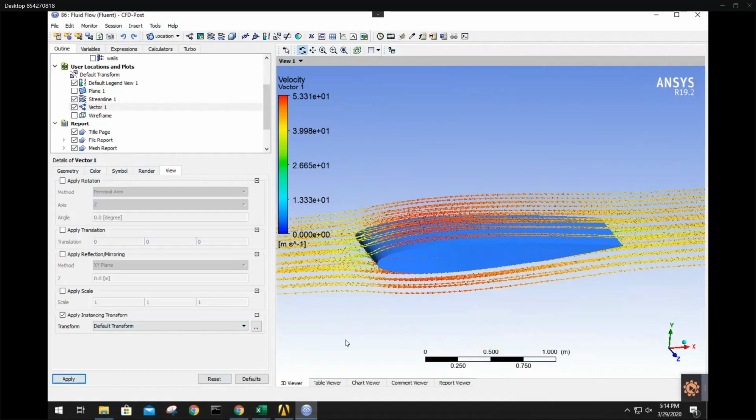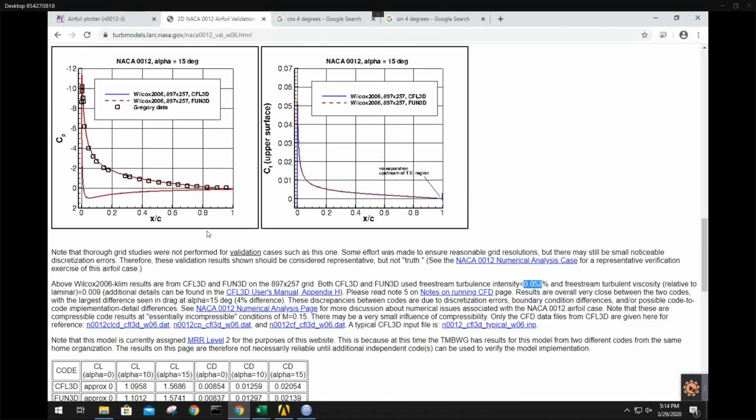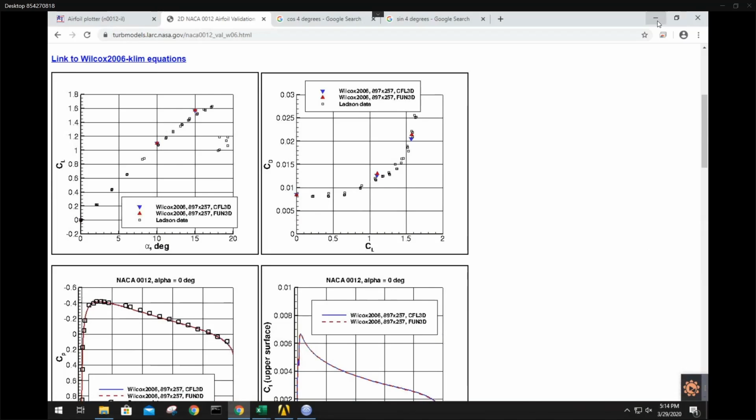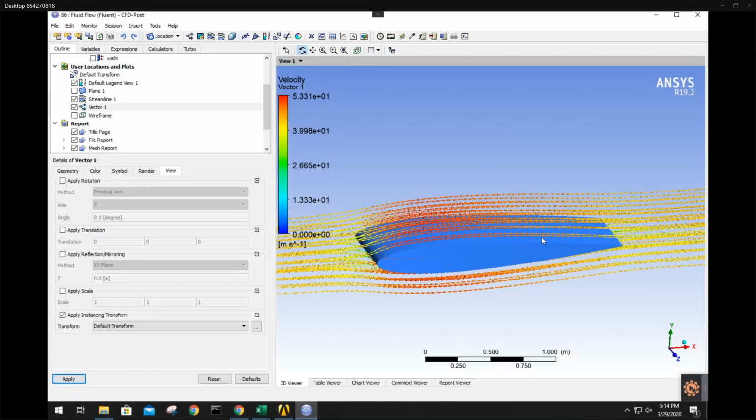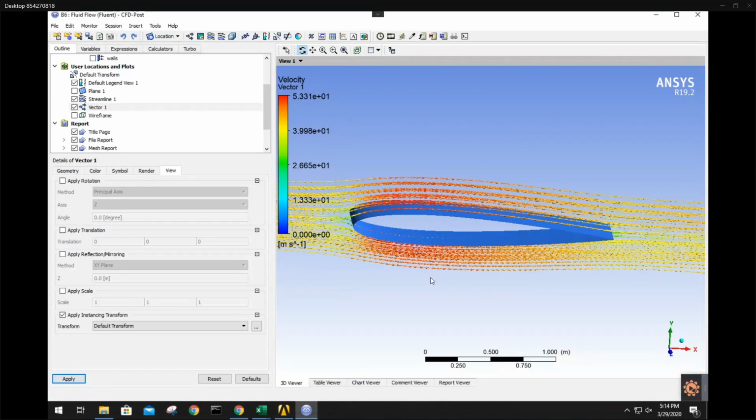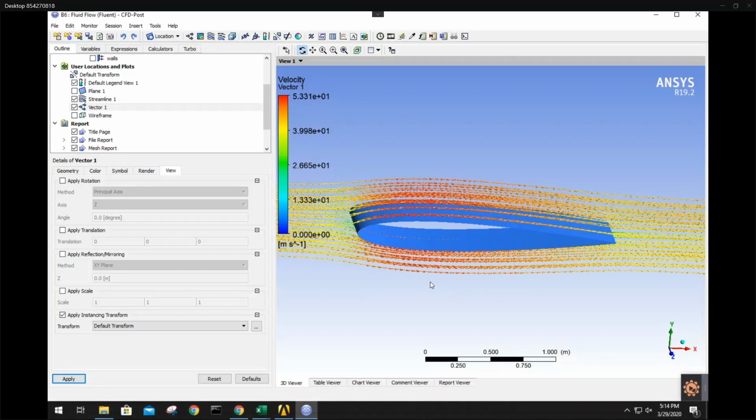I don't know if I showed you, but when I redid this with the corrected reference values, I get the correct amount of drag and the correct amount of lift at 0 and 4 degrees angle of attack. That matches the 2D model, and it should match the 2D model because this is essentially a 2D model. If you want to do a 3D model like an actual wing, that's probably some lofted shape from SolidWorks, I can show that. But hopefully this helps some of you guys.